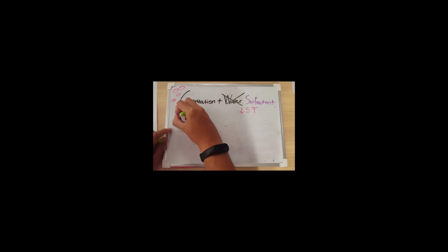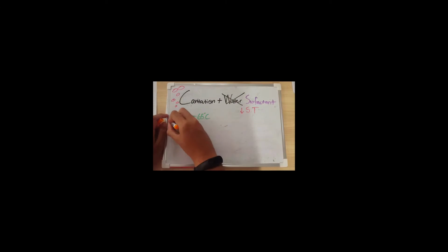Solutions are mostly used warm, at about 50 to 65 degrees Celsius. However, in medical applications, it is generally accepted that cleaning should be at temperatures below 45 degrees Celsius to prevent protein coagulation. The resonant frequency of the transducer determines the size and magnitude of the resonant bubbles.